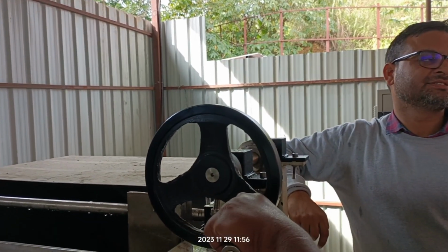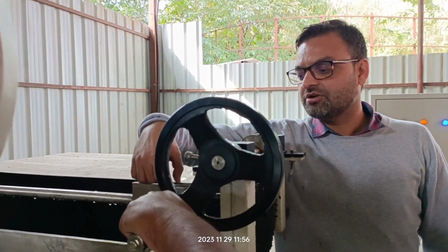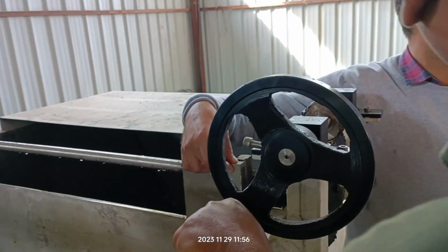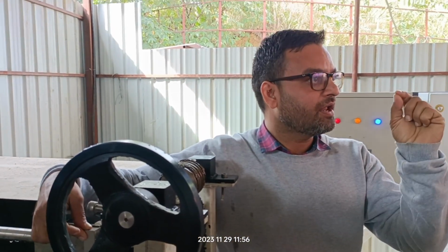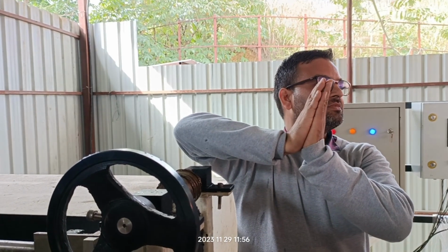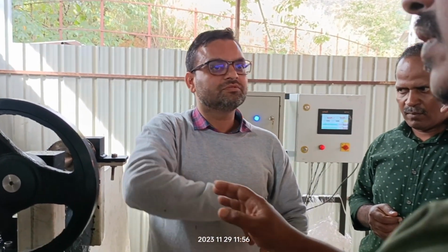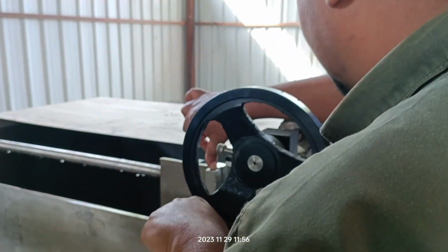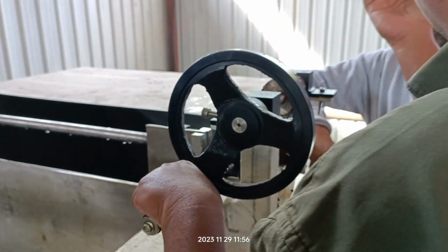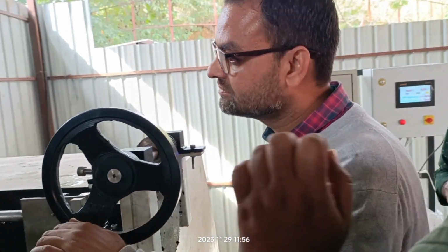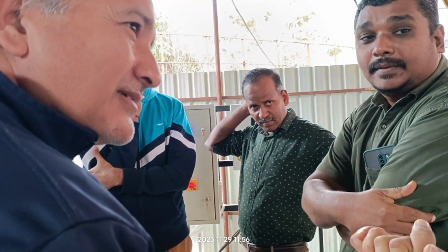It's fixed already. For that only, the surface is already fully there, no? So when you weld this, it will get heated, and when it gets heated, it is going to change its shape a little bit. And 1 mm of deformation will also tighten this, and then it will be too hard. No, it is 16 mm, no? 20 mm it will be. Nothing will happen. Strength is the main motive or leakage?